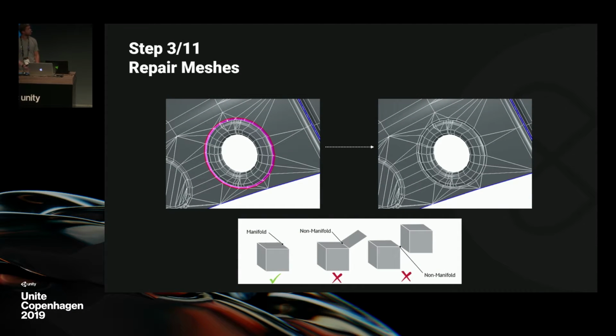So after this tessellation process, some meshes may still be incoherent or show some problems. It can be due to the way the model was originally designed, but also the tolerance we use at tessellation phase. So in this example, we see that some non-manifold surfaces have created redundant polygons, which appear in pink here. So we have a repair mesh function that will identify and fix those issues.